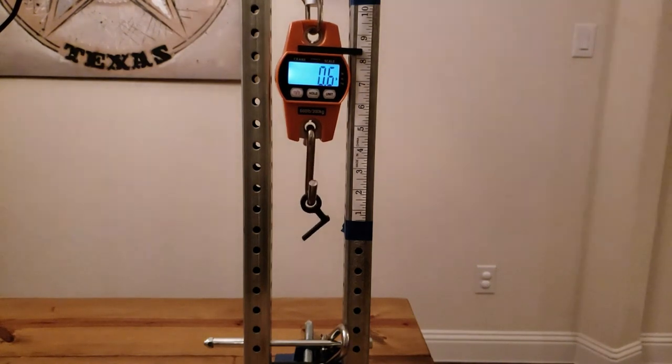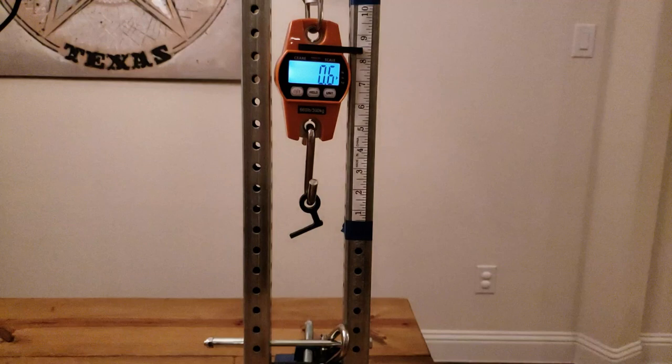So now we can not just say that our displacement for a nonlinear simulation is much more accurate than a linear, but also our ability to predict the point of failure is also much greater with a nonlinear simulation. Of course, if you've done this before, you expect that, but if you've never seen the difference between the two, it's always important to remember that if you are dealing with large displacements, you really need a nonlinear simulation, and if you're running a simulation beyond the yield strength of the material, it is absolutely critical that you consider material nonlinear properties as well.